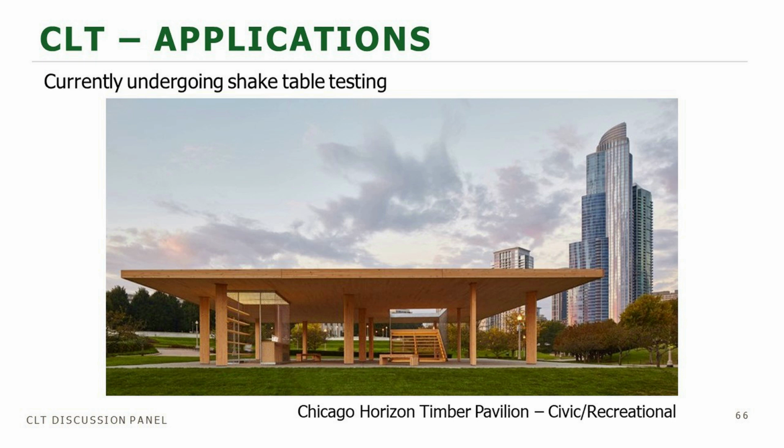Right. Generally, these are not fully exposed elements. It's maybe a soffit or a canopy similar to what we see here, and the moisture content should be less than a fully exposed element. They may have needed some special approvals from the city to put in a project like that, or some professional judgment as well.